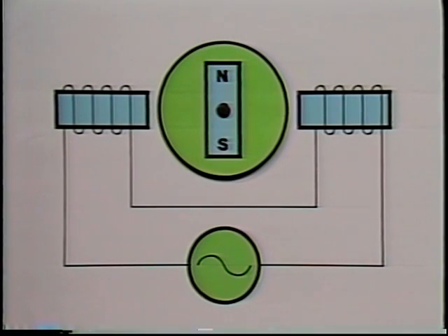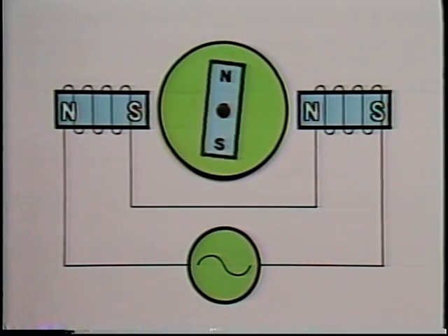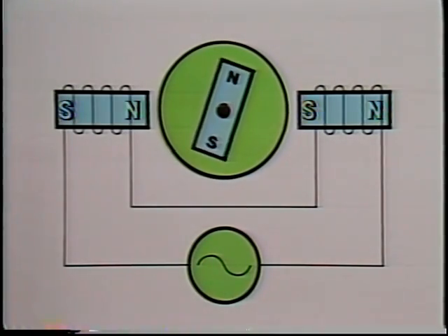The problem is that with single-phase power, the stator poles alternate back and forth but do not actually rotate around the motor in a definite direction. So at startup, the rotor poles are pulled one way and then the other as the current alternates, and do not have a chance to start turning.